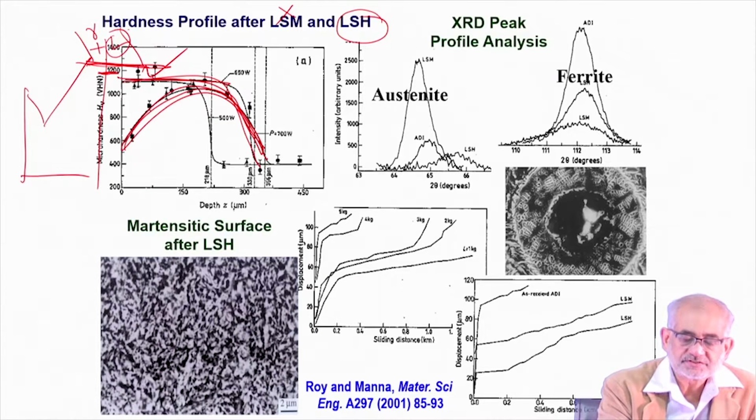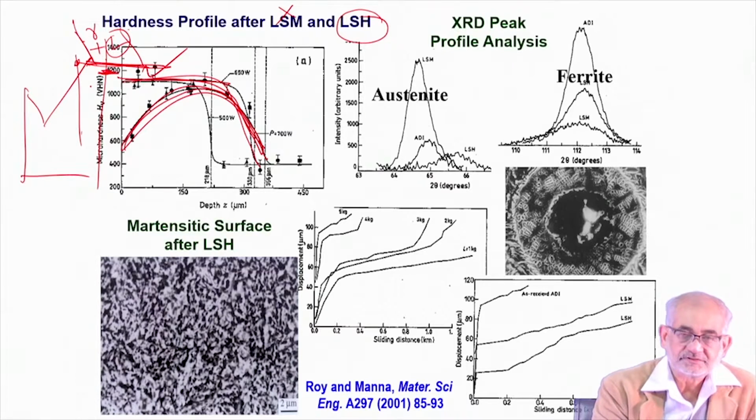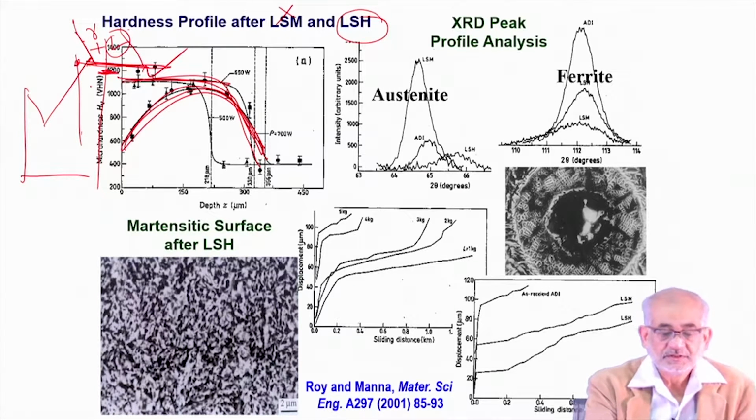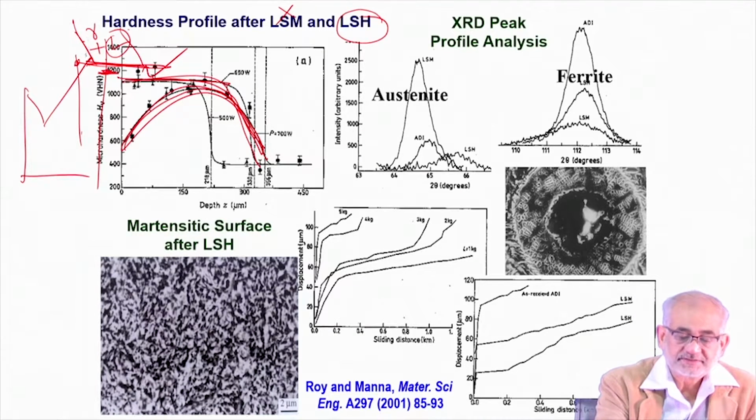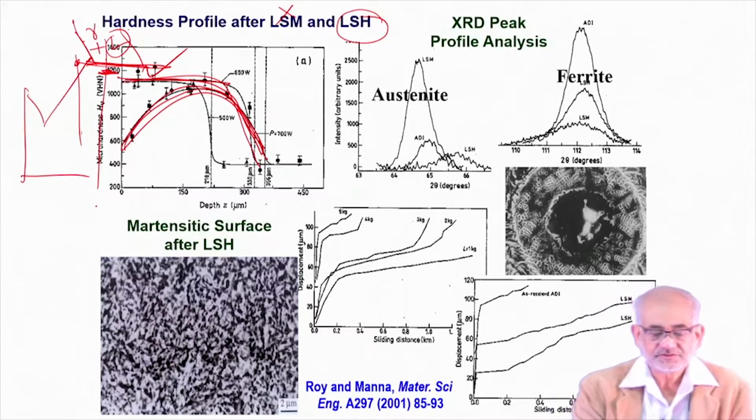If you do not cross this isotherm, if you simply heat up to this region, or if the composition is of lower carbon, if you heat up to this region and don't cross this liquidus line, then solidus line, then obviously you will retain the entire solid. So the entire heating effect will be confined to only solid.